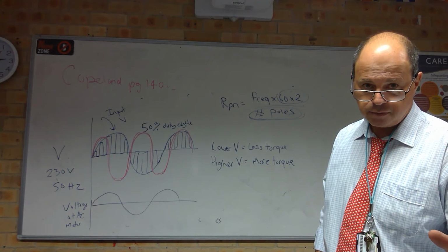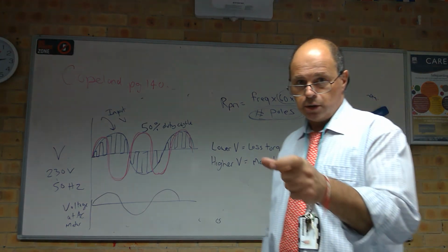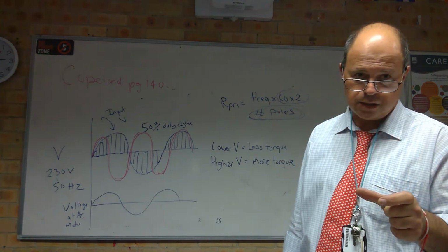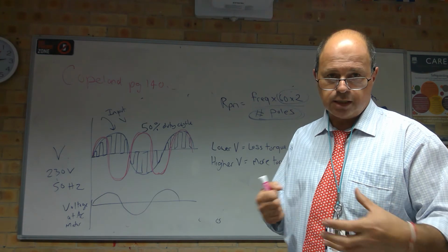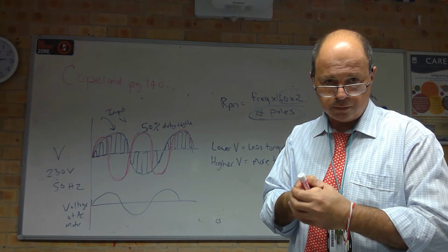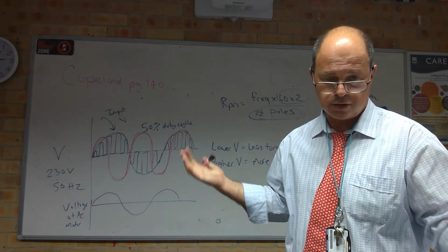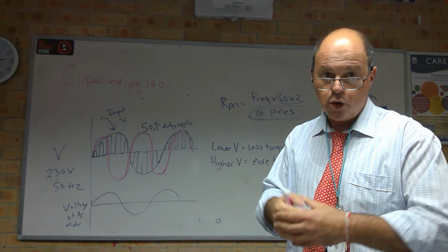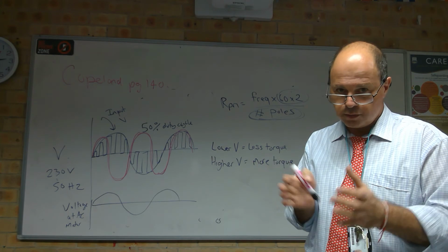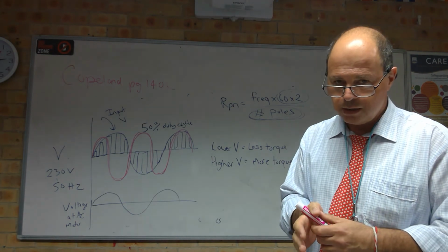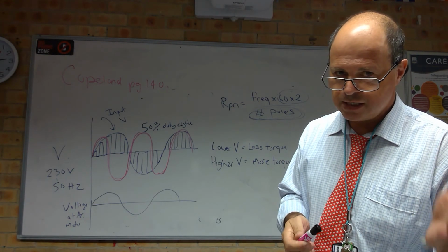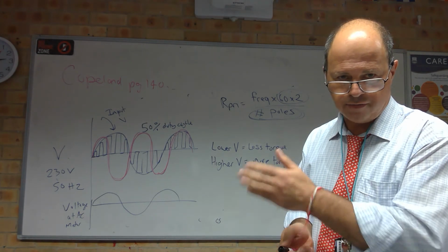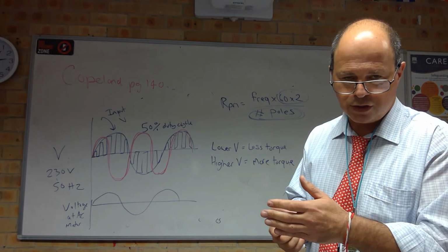According to Faraday's law, you can either make more windings and put the windings on a heavy metal core that's laminated to make a stronger magnetic field, or you can make your transformer smaller with a smaller core if you have a higher frequency, because that higher frequency will induce a higher voltage as well. So that's what they do in a switch mode supply.